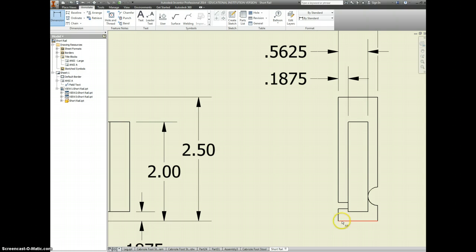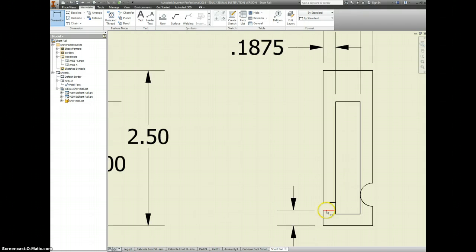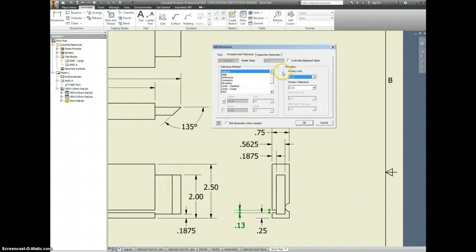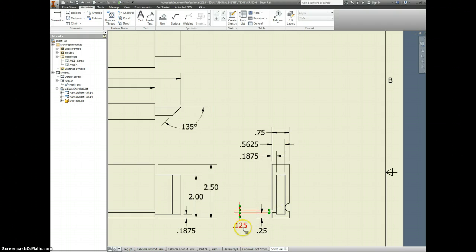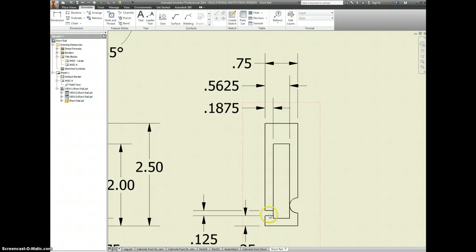Okay, get a little bit of detail over here on this side. I know that this is 1/4 of an inch up, and it's important to note that this is a dimension made from the table saw itself. The width of the blade on the table saw is 0.125. So I'm not going to give that a datum because we're not dimensioning that. We're just saying how far up that is and then showing, yeah, it's a 1/4 inch blade thickness that we need.